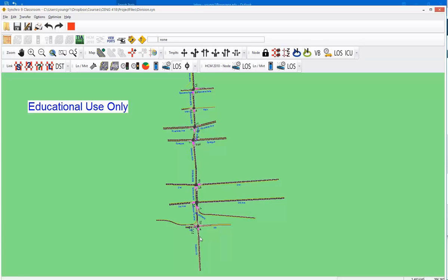And then you're going to be using a second file where I've gone through and adjusted all the volumes so that they represent the future traffic volumes. I've taken the information from the travel forecasting model that we used, I think in the second week of class, and updated it where we have less volume on Division because of the future North Spokane Corridor going in. But then we also see some of the cross traffic increasing because of general increased demand downtown. So with those two things together, we get new volumes.